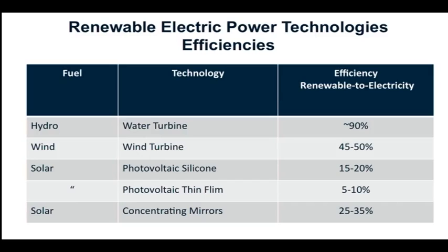That's not a heat cycle, so it's not limited by the second law of thermodynamics in that case. It is limited by the first law, that you can't get more than 100% because you can't get more energy out of it than you put in, than the water has when it goes in.